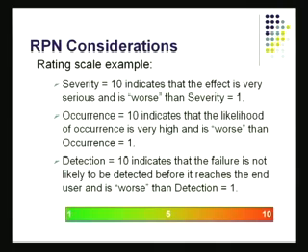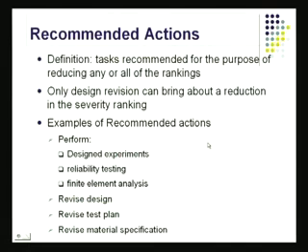And of course, you want to be able to make sure that the high RPN items are all looked at before you go any further. And recommended actions, of course. This is something that you've got to be able to end with when you end up with your FMEA. You've got some FMEA actions there.